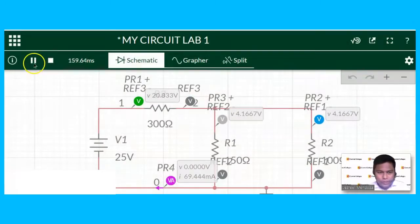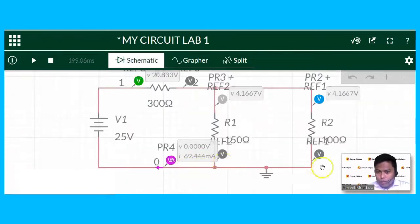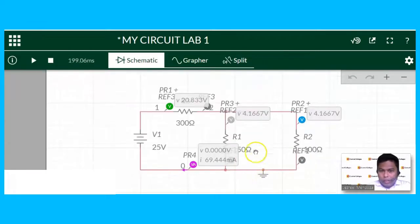Okay, so it is very clear that the voltage for R3 is 20.83 volts. Then for R1 and R2, the same reading of 4.16 volts. At the lower portion, the voltage is 0 because it touches the ground, the reference point.